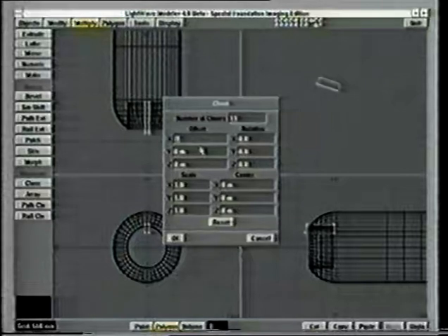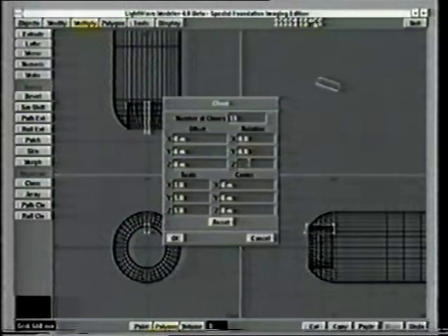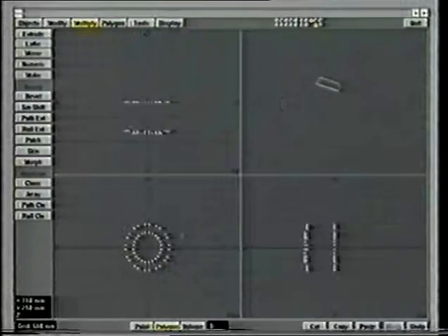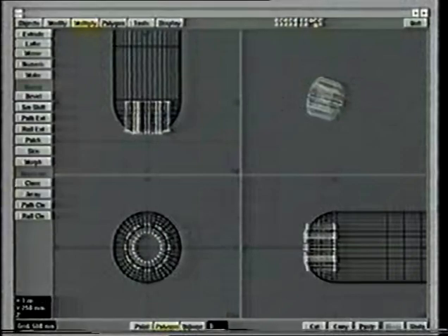There's no offset here. 0. And the rotation around the z-axis will be 30 degrees. Hit it. And there we go. Nice little radial detail. So why do we use 30 degrees there? Obviously it's 360 degrees divided by 12 because we want 12 total.